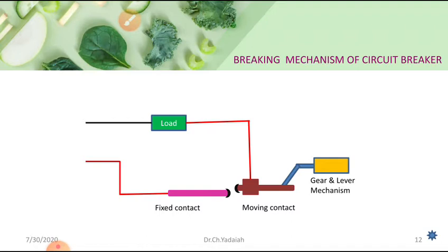So instead of placing the moving and fixed contacts in open atmospheric condition, we place them in a closed vent. Then whatever arc comes can be limited within the chamber. That is the modern circuit breaker. Within the chamber, we add some more media to quench the arc very quickly. That may be oil, exhaust gas, or a puff of air blast, 20 to 30 kg per square centimeter of high pressure air, so that it takes away the ionized particles. That can be seen later.